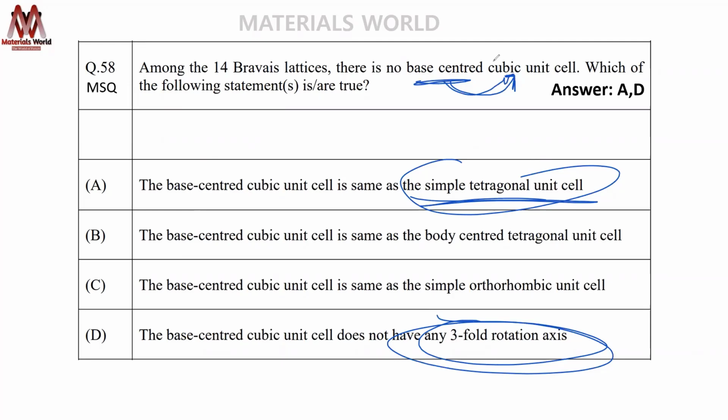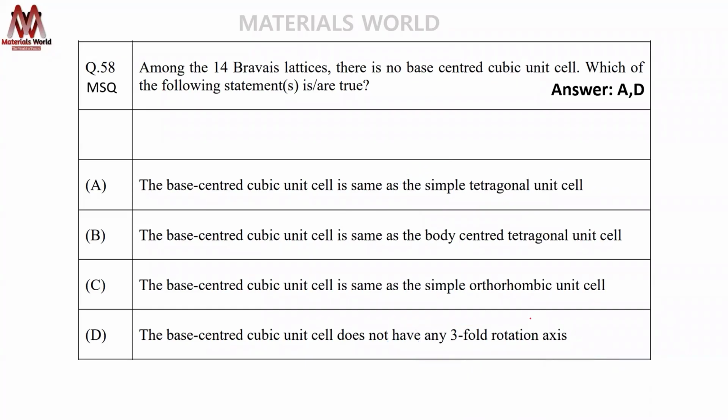It's very simple. Any Bravais lattice which cannot exist because it violates the basic symmetry or point group of that crystal system. For example, in tetragonal it is 4-fold, and in body centered, a 3-fold along the diagonal. In cubic, it's 3-fold. In tetragonal, it's 4-fold. In hexagonal, it's 6-fold. Got my point? That's why you cannot have it.